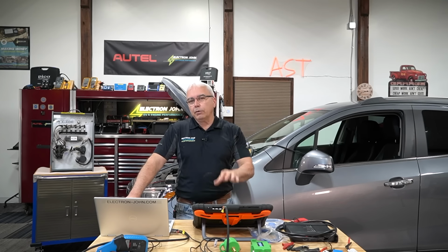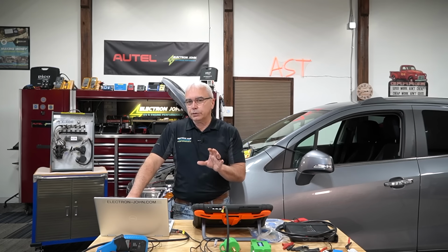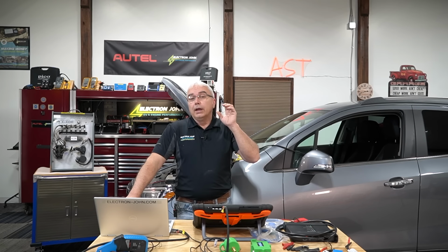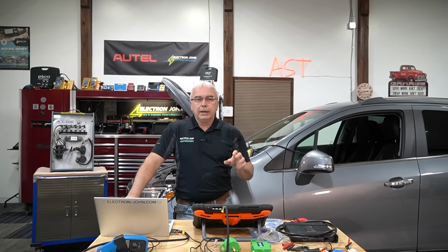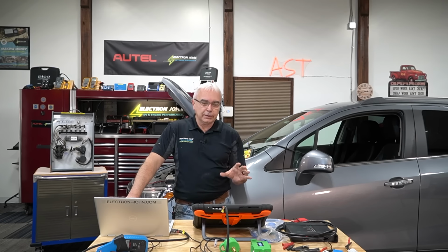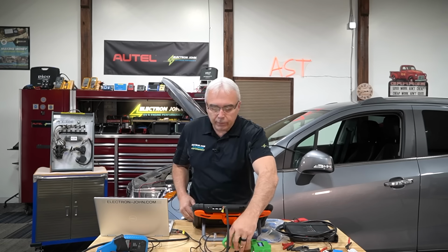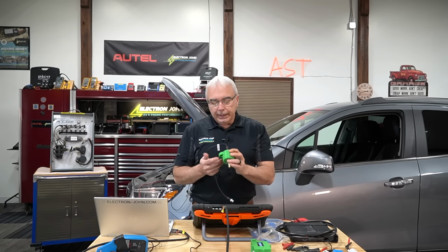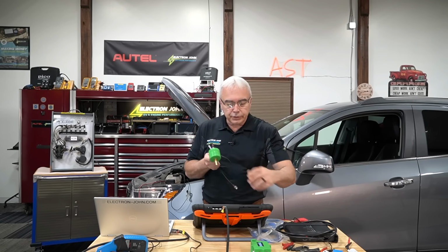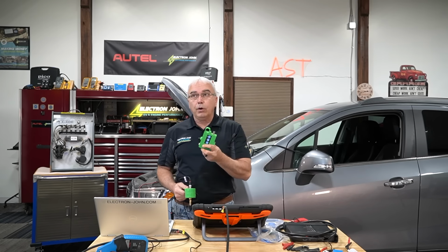I want to talk about the test results and what I use some of these for, because I'm just going to throw some different diagnostic scenarios out there and show you some of the advanced testing procedures you can do with your scope. So I've got up on the table in front of me a series of different types of tooling. And here's a pressure transducer. I've got the Pico one right here that's made to go inside a cylinder, and it can also go to a vacuum hose or whatever else I want.